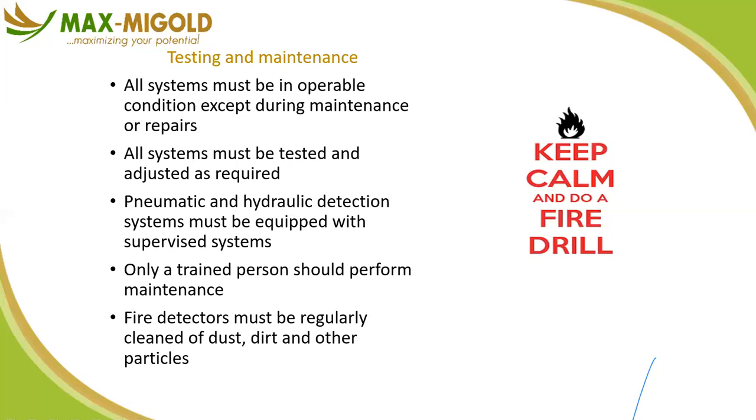All right. So don't just go and remove something, maybe your fire engine or some safety critical element, under the name of maintenance. You need to do what we call issuance of impairment notice. You need to notify who needs to be notified. Your insurance, your directors, even all the employees, and of course the fire service, to say for the next 1 week, our fire pump will not be available due to the annual maintenance program. That is allowed. But then the question is, for that period of 1 week, what are we going to do?